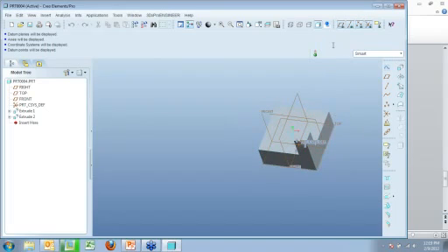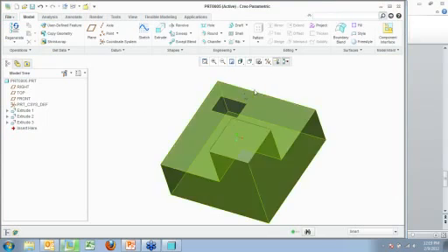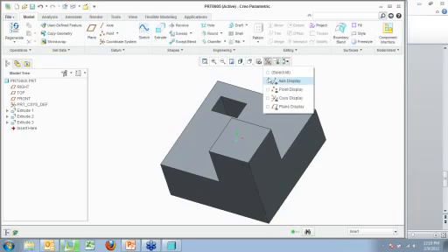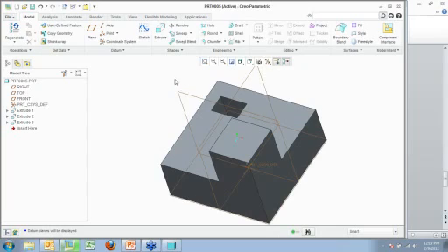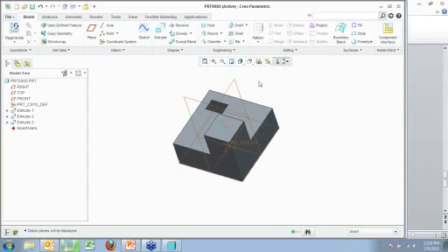Well, the way you'd have to do that is set a Config Pro option to turn those off by default, or when you open it, come in and go up here and click all these off. Well, now in Creo Parametric, they're all here under one button with a checkbox. You can turn them all on and off at the same time. So that saves you a little bit more time there.